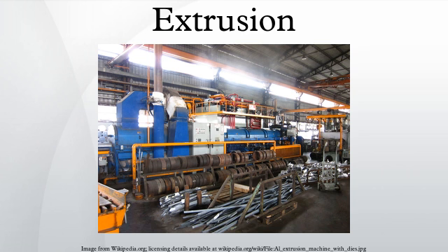Aluminium hot extrusion die. Cold extrusion is done at room temperature or near room temperature. The advantages of this over hot extrusion are the lack of oxidation, higher strength due to cold working, closer tolerances, good surface finish, and fast extrusion speeds if the material is subject to hot shortness.